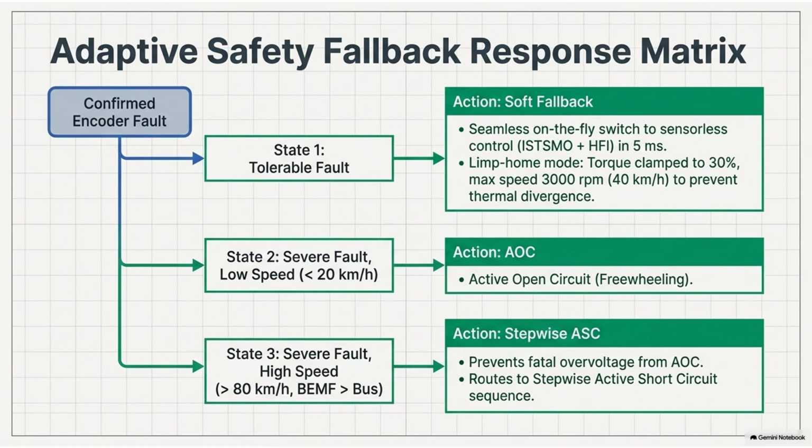Right. Normal Class 2 or Class 3 capacitors like X7R or Y5V, they use barium titanate dielectrics. And when those get hot or cold, their capacitance value drifts wildly. Yeah. And if your filter's capacitance changes, the cutoff frequency of your low-pass filter shifts, meaning high-frequency noise suddenly gets through to the processor. But Class 1 C0G capacitors do not use barium titanate. They use a temperature-compensating ceramic dielectric that is incredibly stable. They have a temperature coefficient of essentially 0, right? Specifically 0 plus or minus 30 parts per million per degree Celsius across the entire extreme temperature range. Their thermal drift is virtually non-existent.